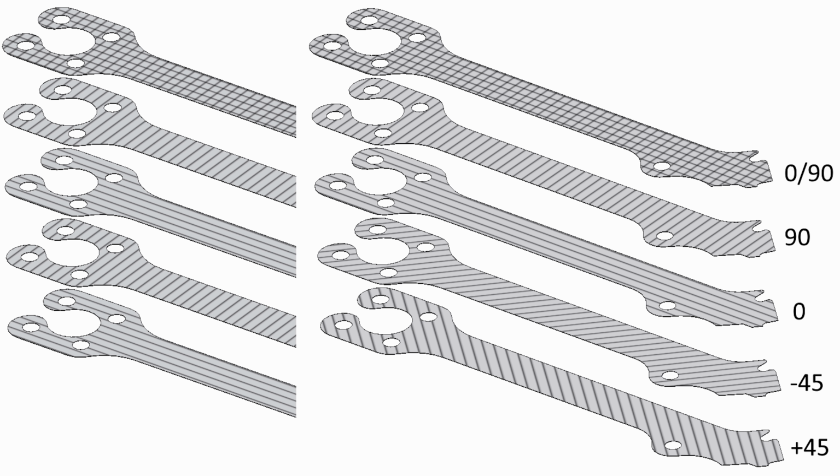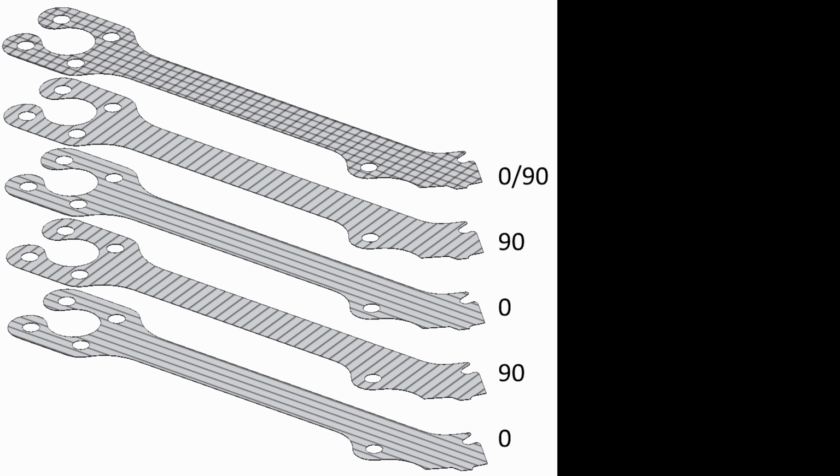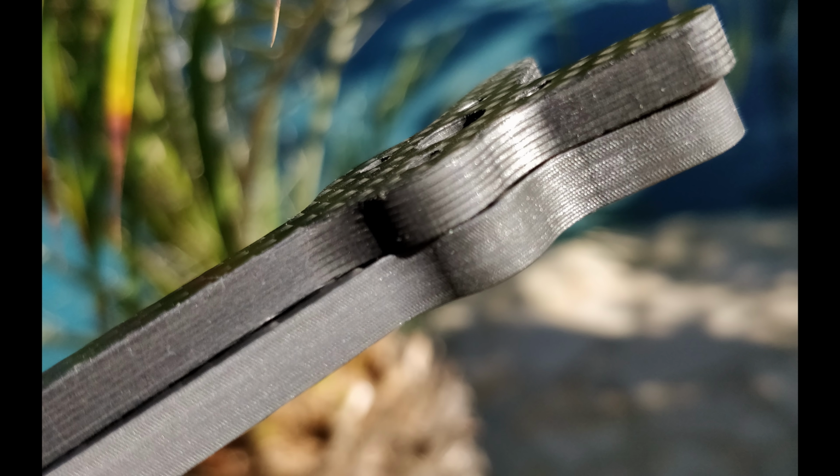The laminates, or the pre-finished products, which are the pre-impregnated laminates: if you look at the edges of your carbon fiber arms, if you have a 5 mm carbon fiber, you might notice that you have 5 layers that look like they're glued together. That's because the carbon fiber product comes to the person making the different thicknesses of a sheet in 1 mm thickness layers. If they want 5 mm, they just slap 5 of those layers together and cook them together.